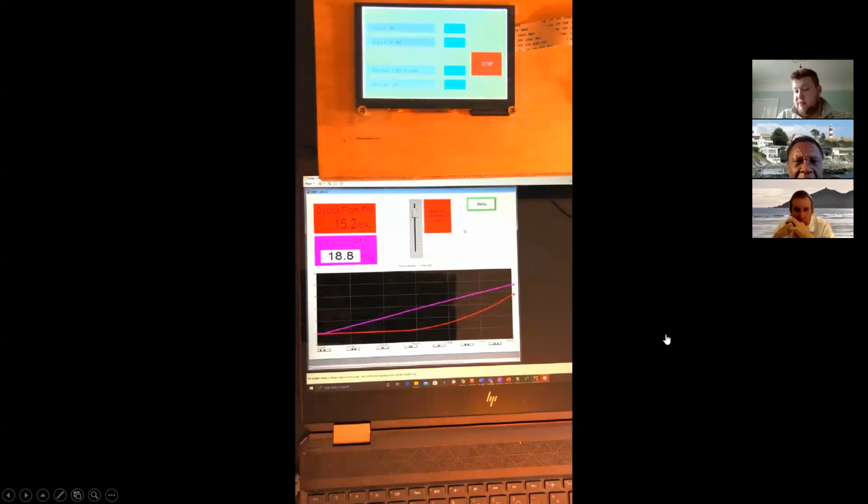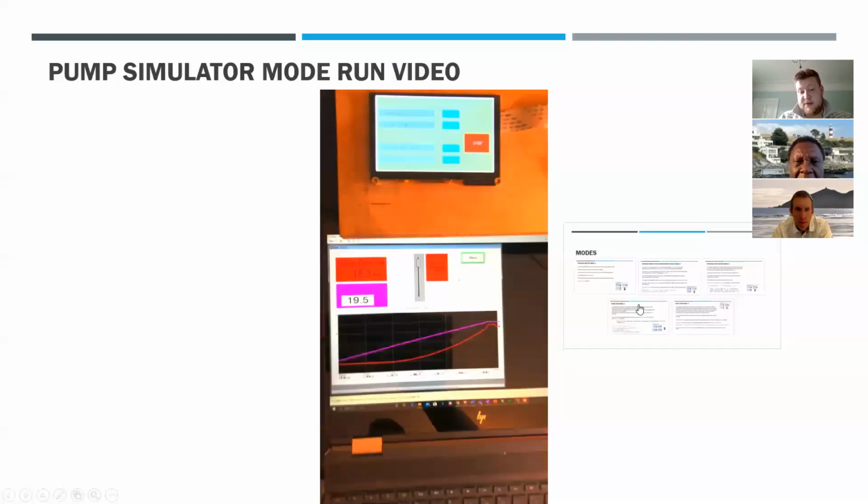So you can slowly see the red line is now outputting the characteristics that we placed inside of those set points. At 19.5 milliamps, it was asking 19.5 milliamps into the system. We said that it needed to limit it to 18.3 milliamps out. So as you put the input into the system, it then outputs the characteristic curve.